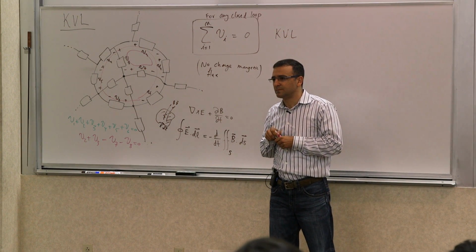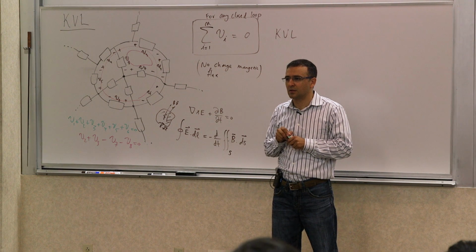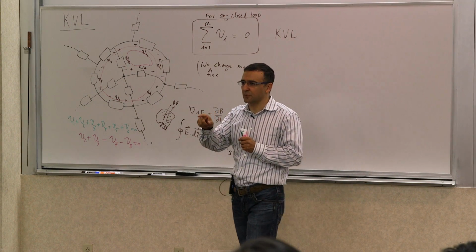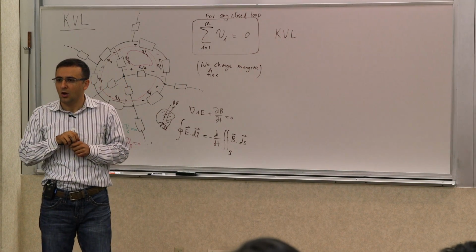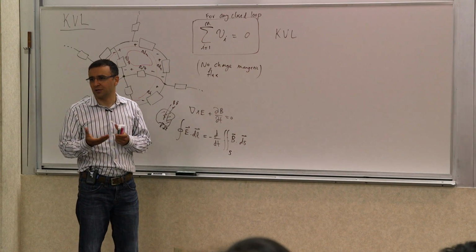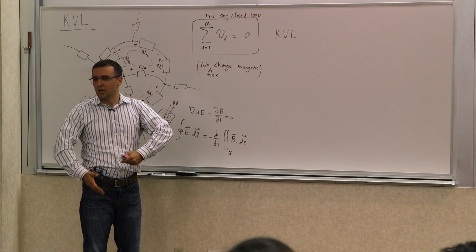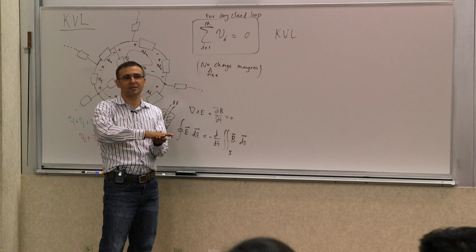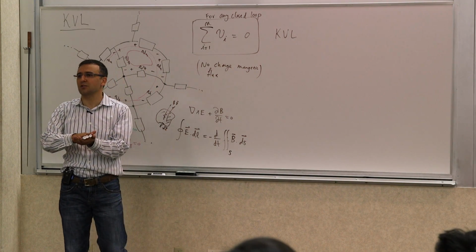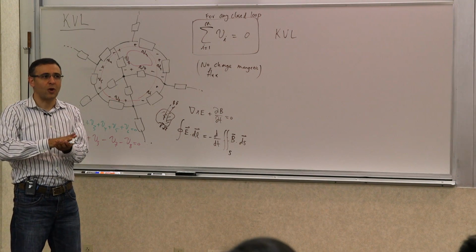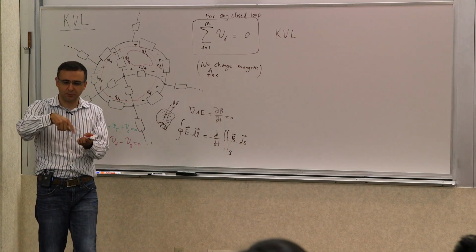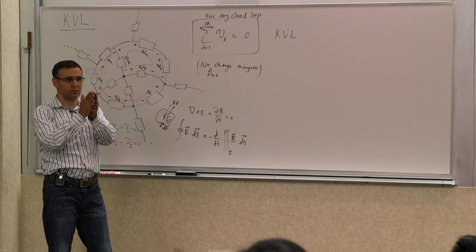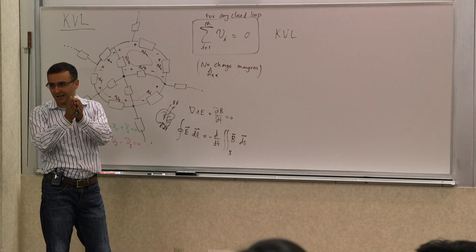Besides antennas, is there any application where you use a chain of magnetic flux to violate KVL for some reason? And you mean besides transformers? Yes. If you're talking about KVL. Oh yes, everything. Magnetic induction essentially, all of that. For these proximity chargers, which some phones have, those are essentially magnetic induction charging. You create a primary where you alternate the magnetic field and couple energy into the secondary that's picked up. So you do it through space, through the magnetic coupling, without having an electrical contact.